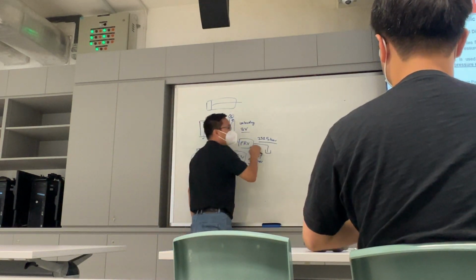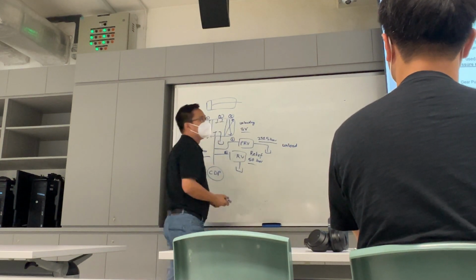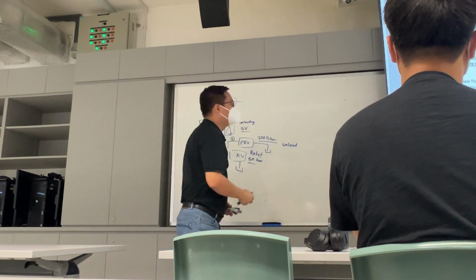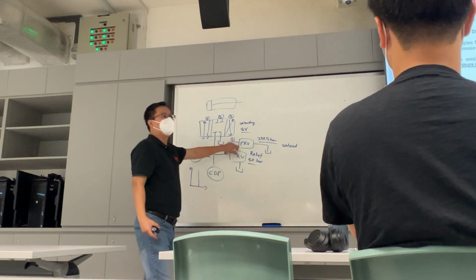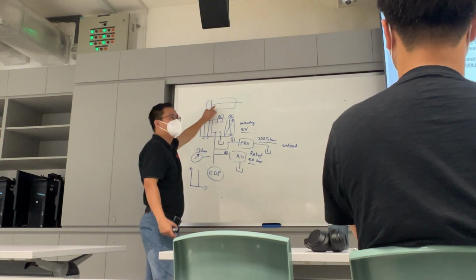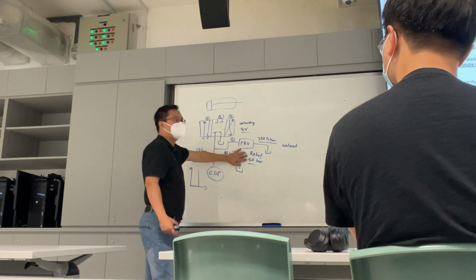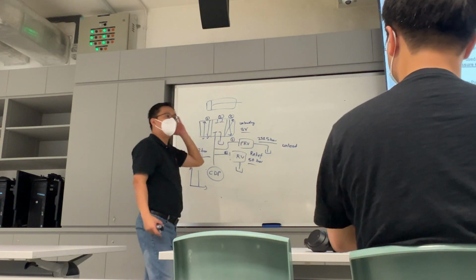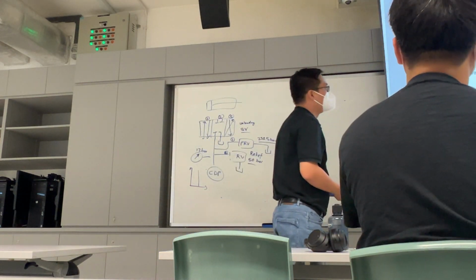And if the fluid goes out from the pressure regulator valve, we also use the word unloading. Follow so far? So this statement is to tell you that for a constant displacement pump, you must have a pressure regulator or unloading valve. If not, you're asking for trouble. Because first, you cannot control the demand. Second, you don't have this. Let's say you don't have a relief valve, you don't have this, the system will explode. Alright, so please read the question properly. Okay?